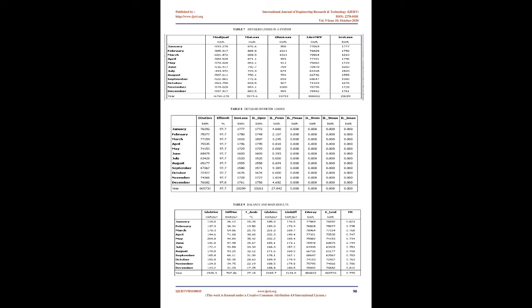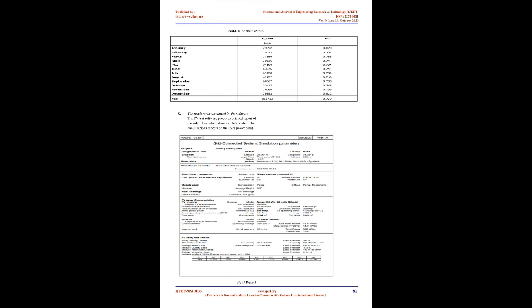Horizon. Horizon profile may be defined manually by a set of azimuth/height points in degrees. These may be from on-site measurements, using land surveyors' instruments like a compass. They can also be imported from several sources. Solmetric SunEye instrument. This is a computerized instrument using a fisheye type camera for the recording of the environmental masks. It provides a horizon height for each degree of azimuth, i.e. 360 points.